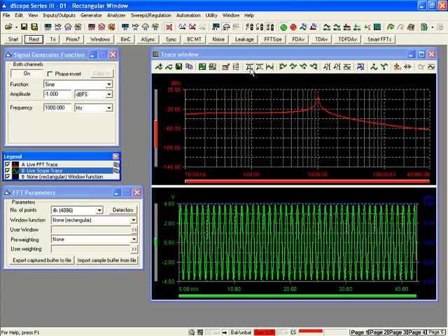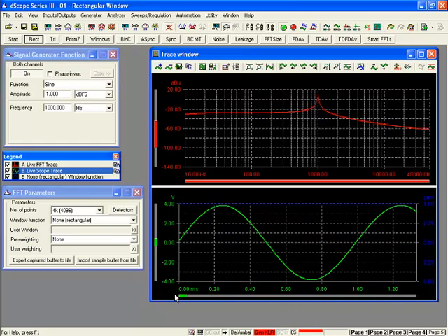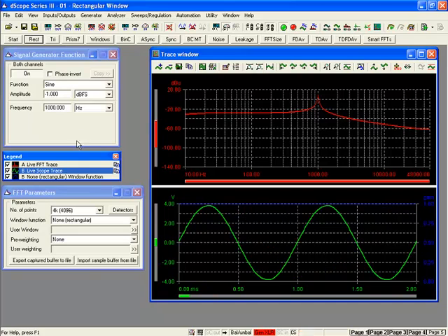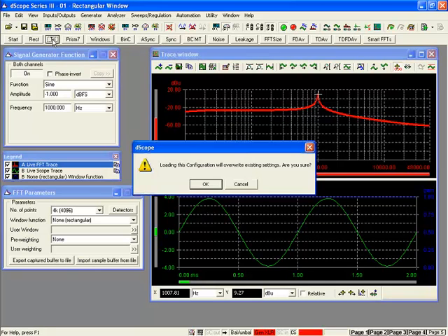So the resulting time domain trace is here on the lower portion of the trace window. You can see that this is our sinusoidal signal. And in the red upper trace here, we have our resulting FFT. And we can discriminate the sinusoidal component here. There's a clear peak in the FFT spectrum at around about 1 kilohertz where we'd expect it. But the FFT doesn't really show us anything more than that. There is insufficient dynamic range with this particular combination of signal and window function to reveal anything useful about the signal. So let's try the triangular window then.